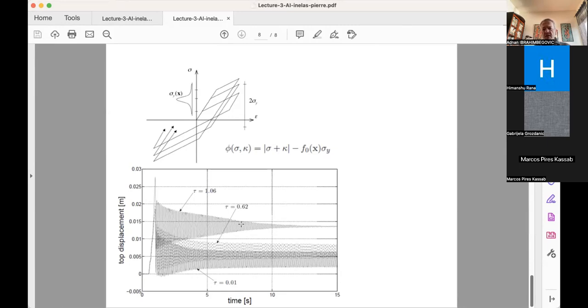I have to say this is a really high hope. If you really want to do that properly, you have to take into account something called size effect. Namely, if you have a composite material and you're able to do testing on a small specimen, you cannot be sure that the result from the small specimen will be the same in terms of failure and fracture pattern, and so on and so forth, as in the large structure.